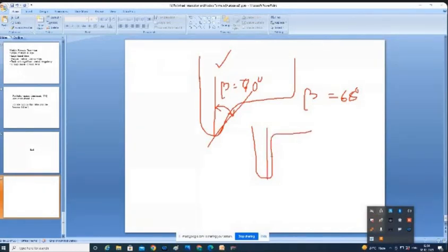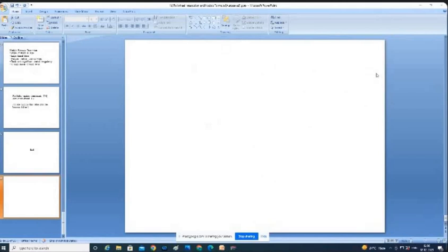So this angle between these is called sharp flange. That is why for locos we start at 68 degrees, and for coaching wheels and wagon wheels we start at 70 degrees. This angle is very, very important for us. If it becomes 90 degrees, it is called a sharp flange. When the beta becomes 90 degrees, that is called a sharp flange. So the beta value, understood all of you?